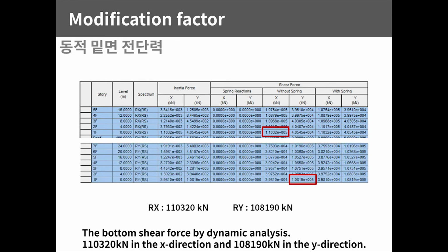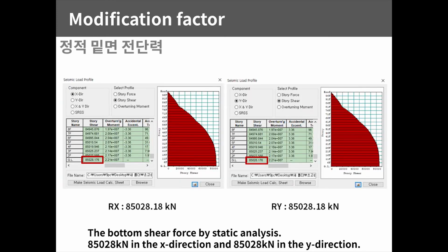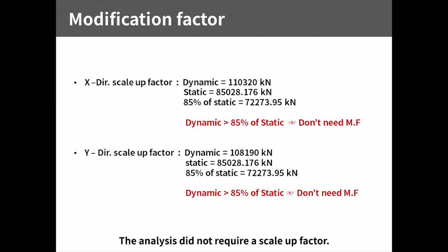The base shear force by dynamic analysis: 110,320 kN in the x direction and 108,190 kN in the y direction. The base shear force by static analysis: 85,028 kN in the x direction and 85,028 kN in the y direction. The analysis did not require a scale-up factor.